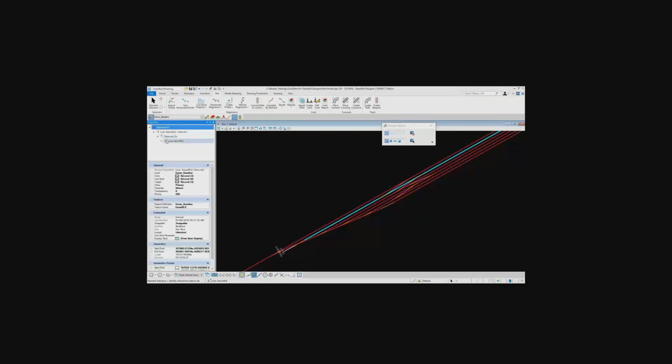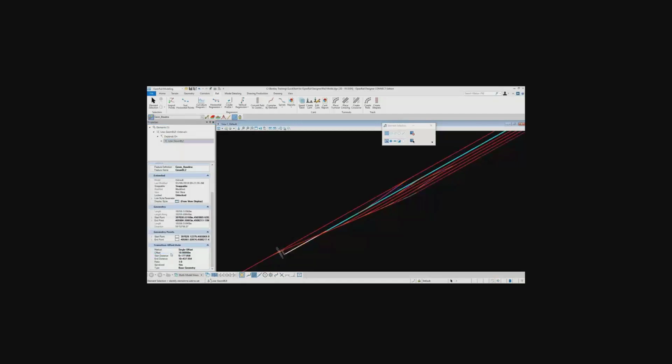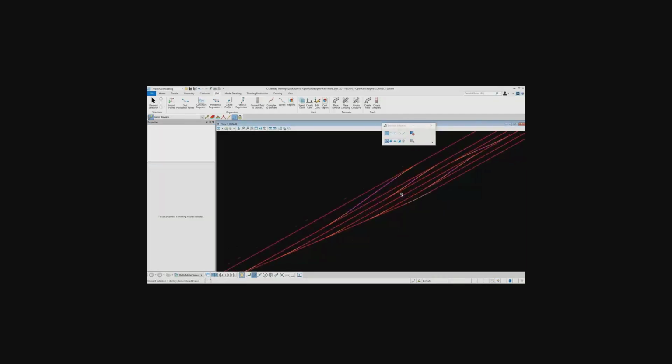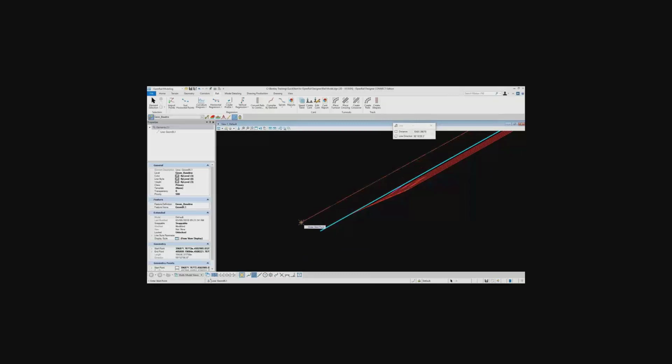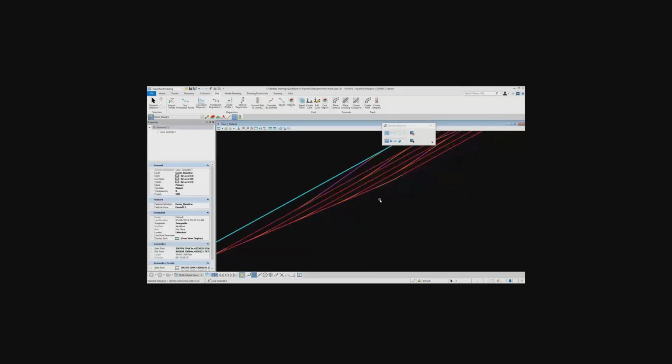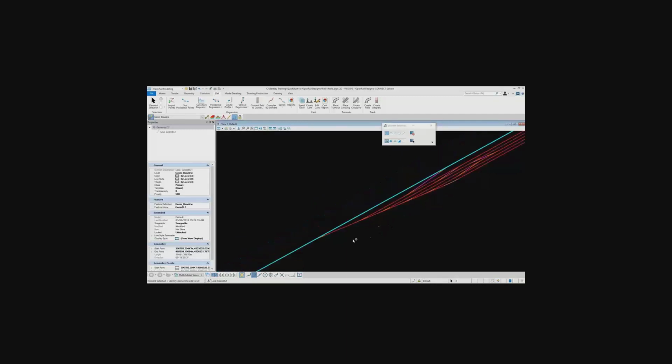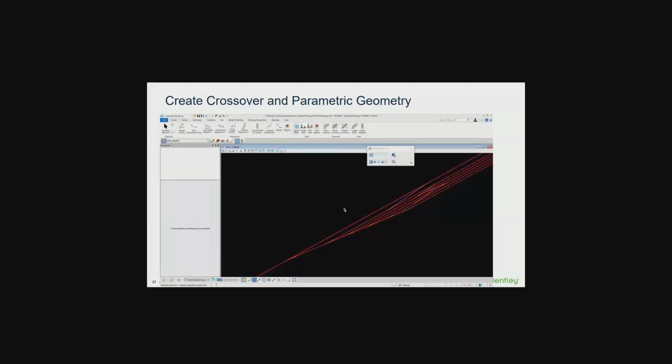But the gist here is that every time you're creating turnouts or even some simple geometries, at any point these geometries will be updated. Notice how dynamic the updates are. I'm exaggeratedly moving the main alignment, but notice how the other alignments are following the main one. Even if I change the chainage attachment of the yard, the other alignments would follow as well.